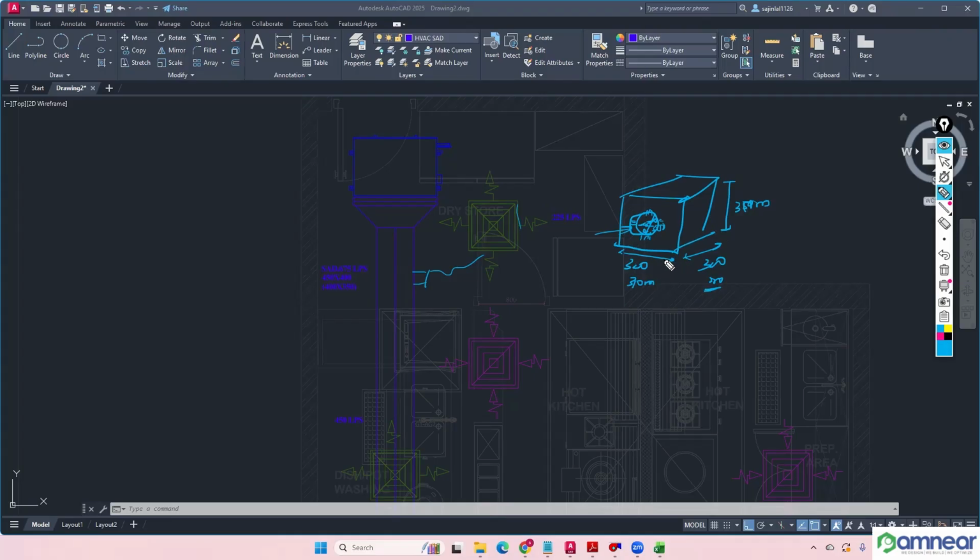Okay, so the plenum box, see, even if the flexible duct diameter is less than 300, 25 mm allowances we have to provide extra, because inside the plenum boxes we need to provide acoustic lining. That acoustic lining allowance has to be provided. So always the plenum size should be 25 mm higher than the demand, then only we can accommodate it. Okay, so for my case, I need the plenum of 350, 350, height 350.